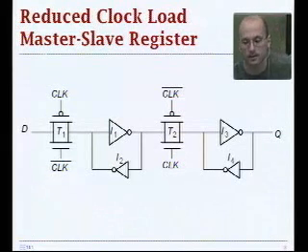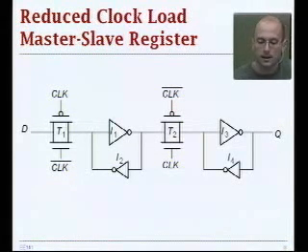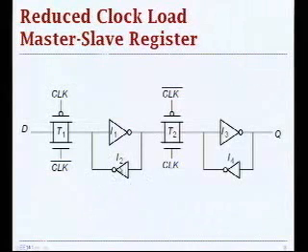I don't want to do that necessarily. So now the idea is, let's do the overpowering approach, but make sure that this feedback transistor is sized appreciably small, so that when you, for example, want to inject a new value at the first stage, you open this transmission gate, and the drive strength of that transmission gate has to be sufficiently high, such that you can overpower this inverter and achieve the switching threshold of this inverter I1.